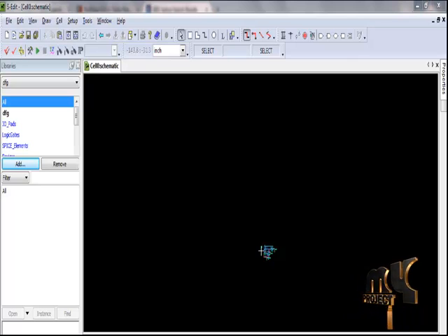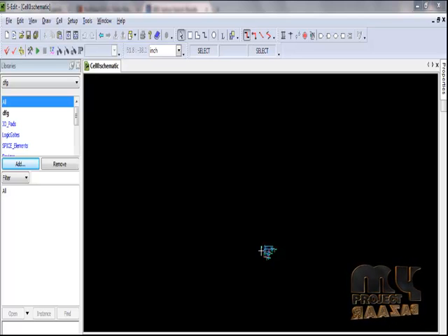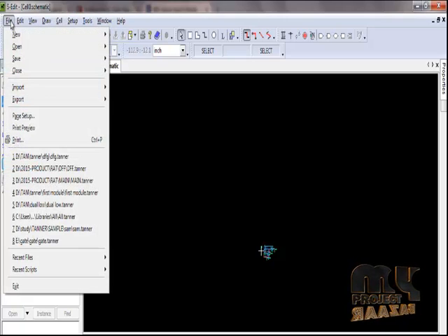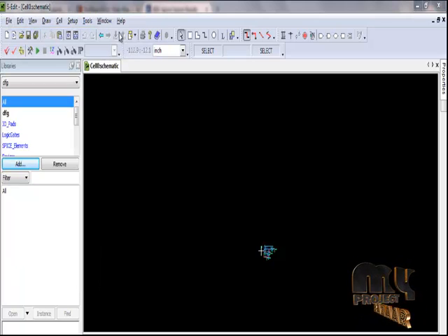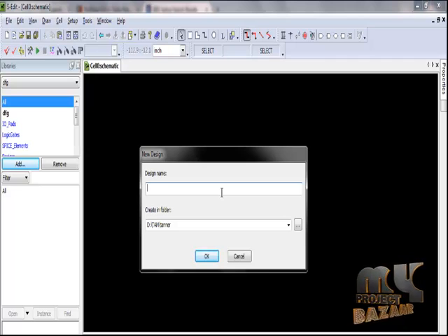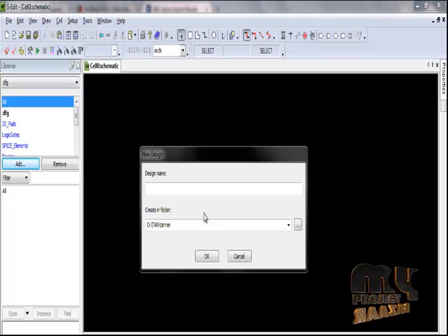Now we are going to discuss the running procedure of our product. Our product can be implemented using the Tanner EDA tool version 13.0, using different cells to implement our product design. Open the tool window and create your own file from the File option, New file, New design. Now we create the design name in the given folder.